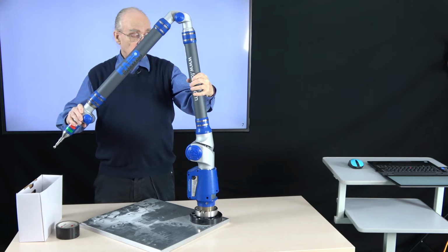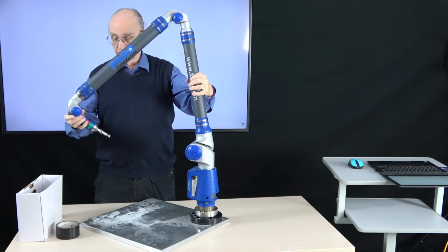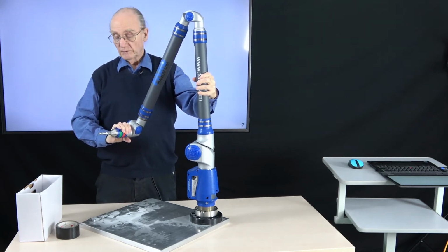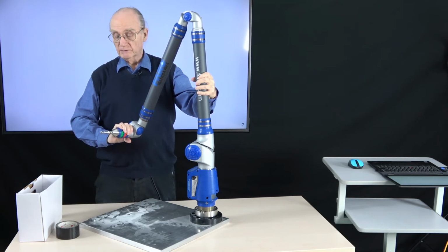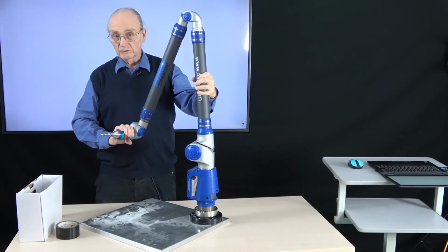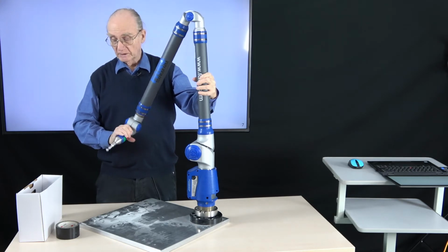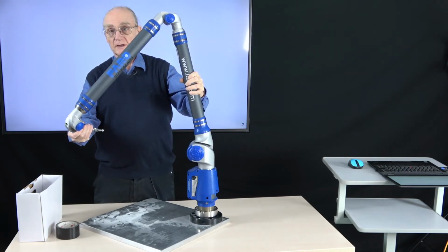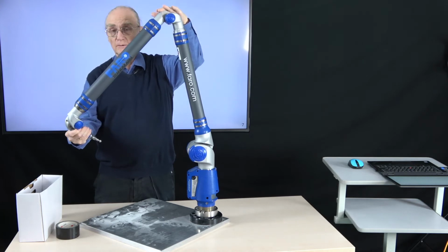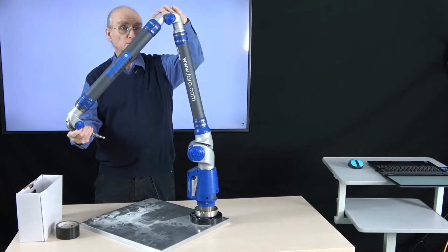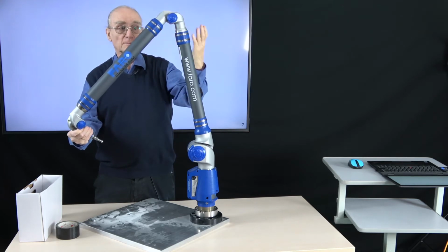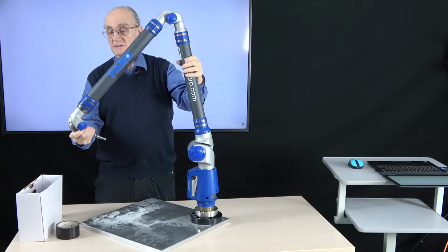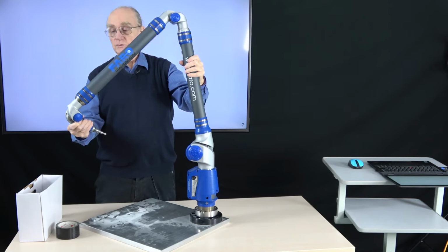The second is that we would like to measure a point not only from one side, but also from the other side. That means we want to specify not only the x, y, z coordinates, but also the normal of the measuring activity. So from here or from here. So we have 5 degrees of freedom, and if we would have only 5 degrees of freedom, that means 5 angles, we would be limited in the range of possible configurations, and this would be a little bit awkward to do the measuring easily. So this is the reason why Faro decided to make a 6 degrees of freedom robot arm to do the measuring.